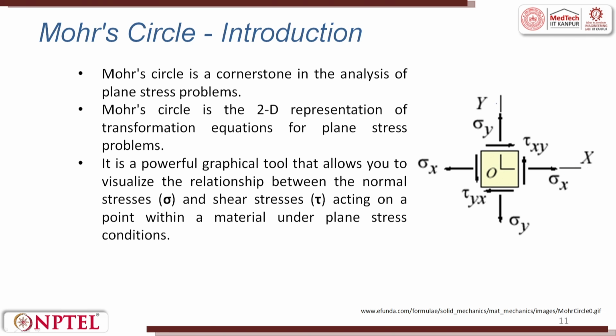In the square you have the x direction, y direction, sigma along the x direction is sigma x, along the y direction is sigma y, and then perpendicular, or I would say shear, comes as tau xy and tau yx. Please note down the notation, right. Otherwise, what will happen if you try to write it inversely? Here if you write tau xy and tau yx, instead of yx you write xy, right, then it is not the correct convention.